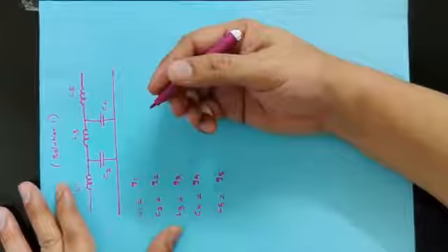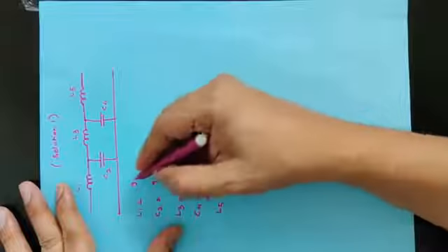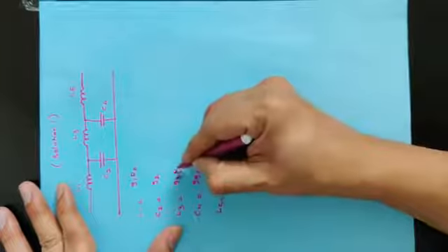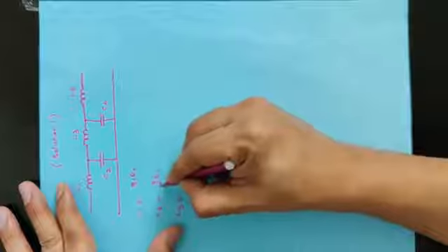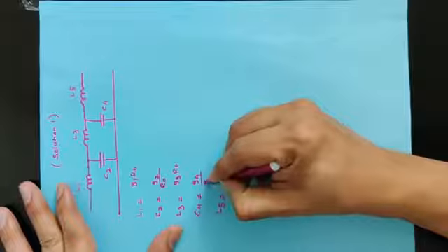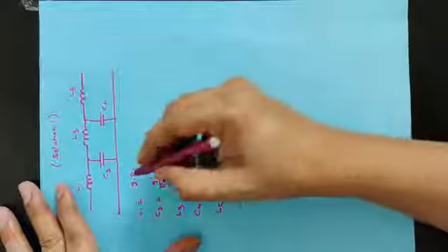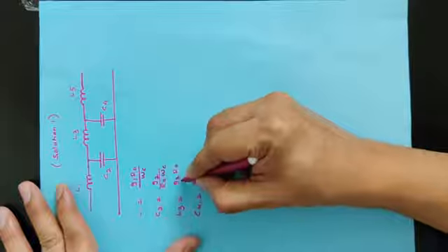Now we have to apply the impedance scaling over here. Impedance scaling is applied like this: for an inductor it will be multiplication by R0, and for the capacitor it will be division by R0. Now we'll apply the frequency scaling. In frequency scaling we divide by the cutoff frequency for all the elements.